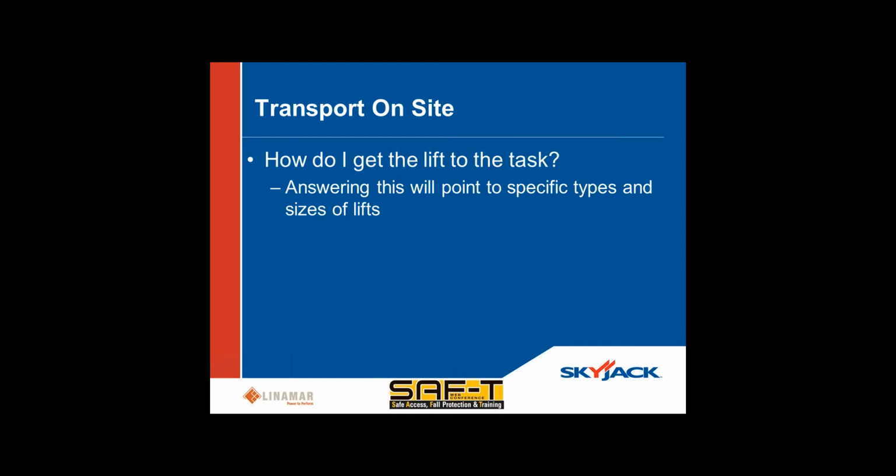Types in that, as I just mentioned, if you have rough terrain to traverse, then you need to obviously have a machine that is capable of traversing rough terrain. And so from a scissor lift and a boom lift application, that generally leads to larger rough terrain lifts that have the abilities to be mobile in unimproved situations or ground conditions.